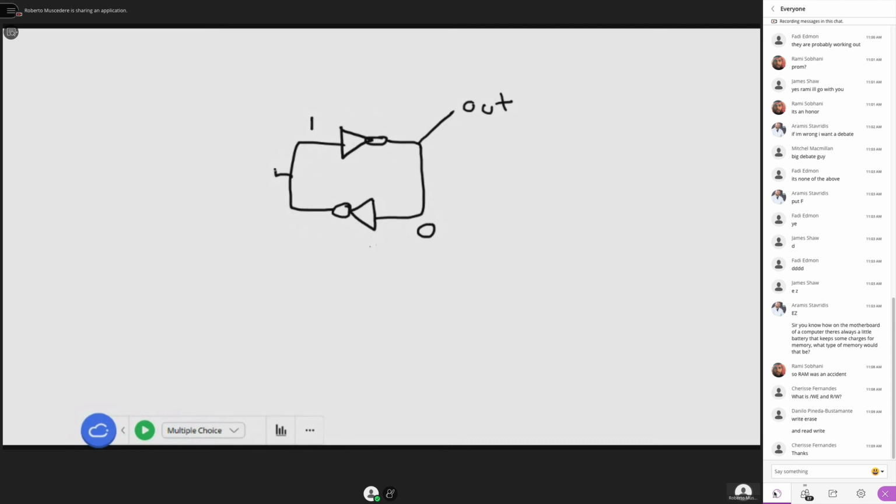So that's why we put in these pass transistors here, which I showed you before. This was M5 and M6, essentially. I think this was M6 and this was M5. So if I want to switch the state, I have to put a 0 here, I have to put a 1 here. So I actually have to update both sides. If I assert M5 and M6, it allows this 0 to pass through, it allows this 1 to pass through, and I've changed the bit. So that's why we need those two transistors on the side to change the bit of memory.